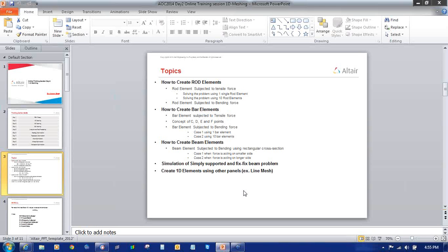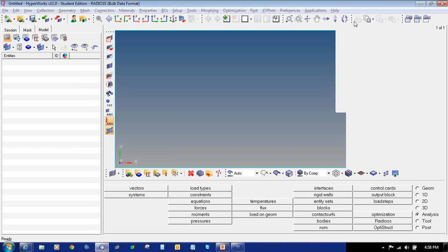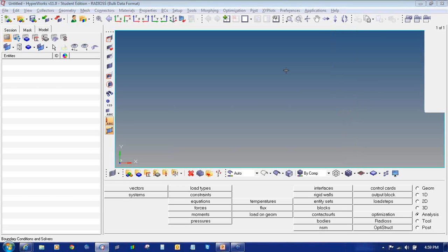So I will show you how to create some structures, what are the different panels available in HyperMesh and how you can create a structure and how you can mesh a structure at once using the 1D meshing options available in HyperMesh. So let's start creating a roll cage structure in HyperMesh itself and then doing the meshing on that roll cage structure at once and then just performing a free run to check all the elements, criteria, material properties, loading conditions, everything, the meshing connectivity.